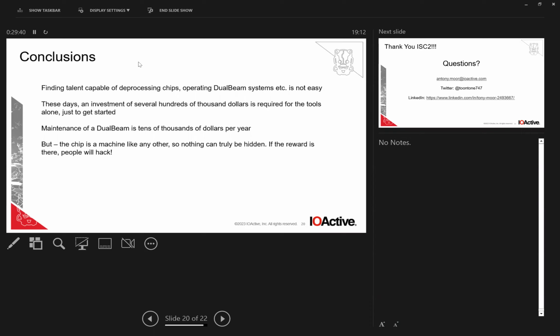If you have something that has millions or billions of transistors, and somebody adds like half a dozen logic cells, you're not going to see it, and it's going to be right at the bottom of the chip. So by physical inspection, you just can't do it. But with deprocessing, yeah, you can use that to take a good example and a bad example, and if you examine the floor of the device at the silicon substrate level, if there are any extra cells or transistors, you have to see them at that level because they have to be on the substrate to function. So you do a scan of a good device and a bad device and do some kind of comparative analysis to make sure that it's 100% correct.